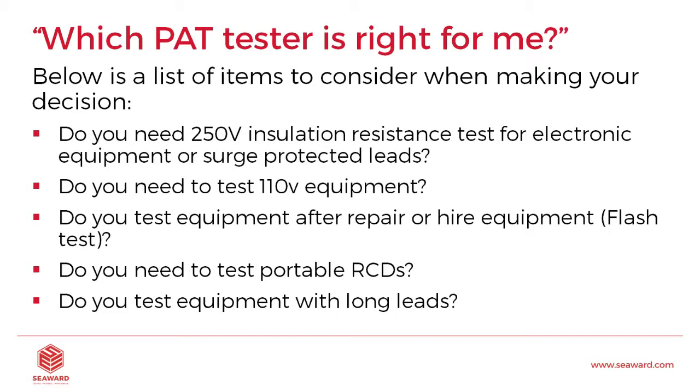Do you need a 250 volt insulation resistance test? Again, something we mentioned earlier on in the webinar was more and more things now are electronic, and could be sensitive to high voltages. Very common now, primarily in offices but stretching beyond that, is surge protected leads. Anything with a surge protected device in is designed to do its job and kick in if you get a spike in the mains. So of course, if you try shunting 500 volts down it from a PAT tester, you could damage not only the surge device in the lead, but you'd get all sorts of weird and wonderful readings and failures on your insulation resistance. So again, a 250 volt insulation test is really something to consider having in your PAT tester.